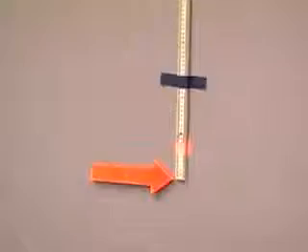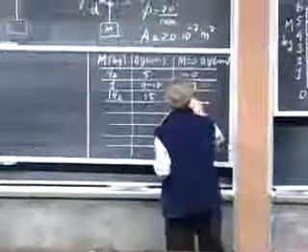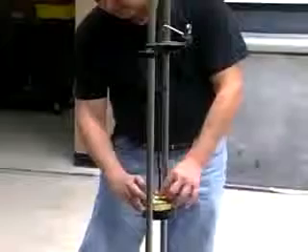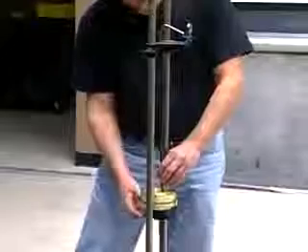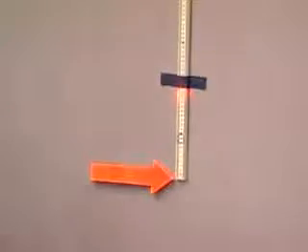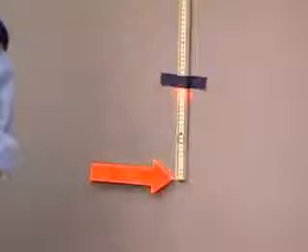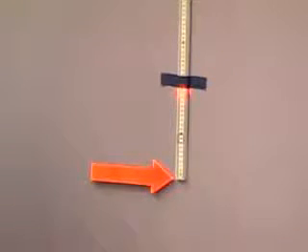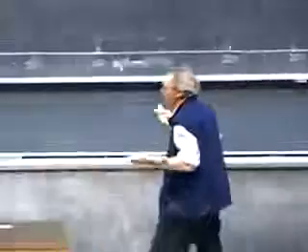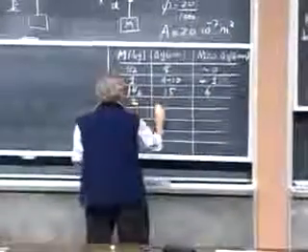Oh, but you see, it no longer wants to return to its original length. It's clearly longer now. Permanent deformation has already occurred. And so we are now something like 6 centimeters. Can you make it 2 kilograms? Two kilograms. If it's linear, you would expect near 20. It's still amazingly linear. It's as close as I can see it to 20, but all these readings are no more accurate than half a centimeter or so. So can you remove the 2 kilograms?